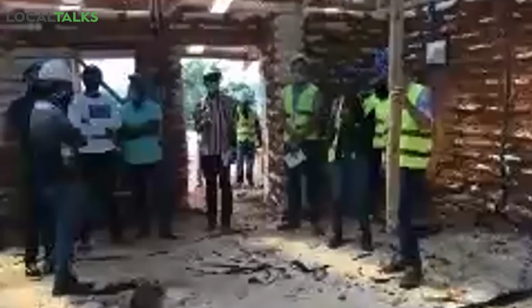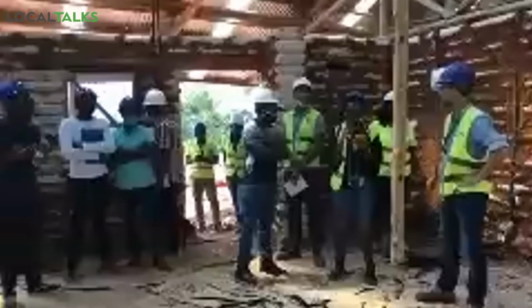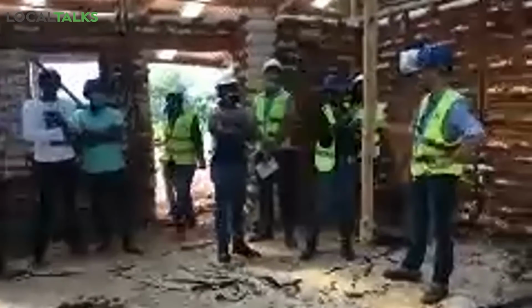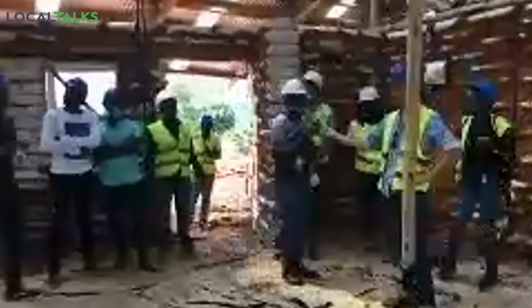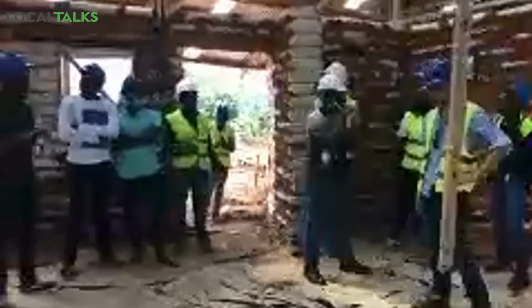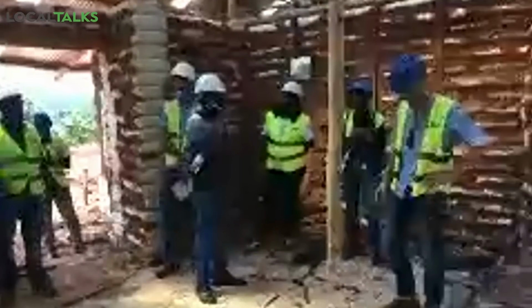So there's a couple of questions here. The first one is from Ivor again. Is there any finish applied on any of the timber or anywhere around that? Preservation method. Yeah, we have dipped this timber in a borax solution, and I think maybe before handover we'll reinstate that by spraying.